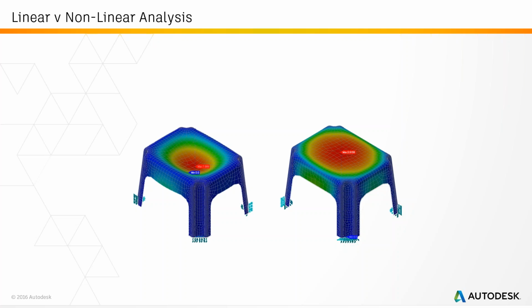In this case, non-linear analysis will be much more accurate because it can account for stiffness changes during loading. There's also material non-linear analysis. So if we go above the yield strength of the material, we can see how it deforms, how it deflects. And sometimes the stresses do actually reduce and the deflections can reduce as well. But we can see if it recovers or not.